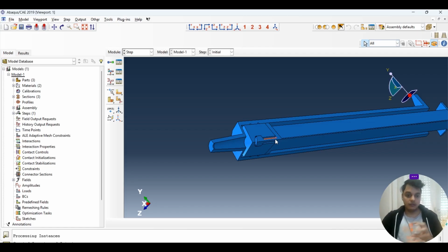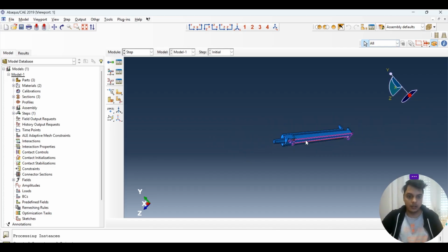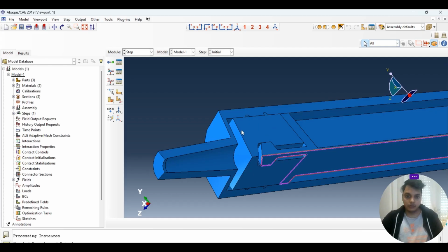And after that, we have to change the friction, that we involve the friction while pushing, and then we have to apply a plunger displacement, or so-called the force in general. So you can apply a load in 2 terms. One is the load, applying the force, or applying the displacement. So in this case, we will apply the displacement in general. So I hope you guys have understood how exactly the steps are defined.